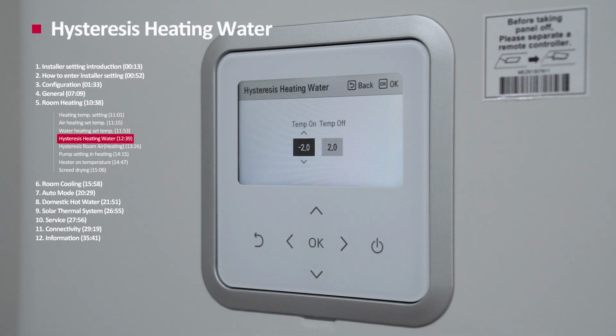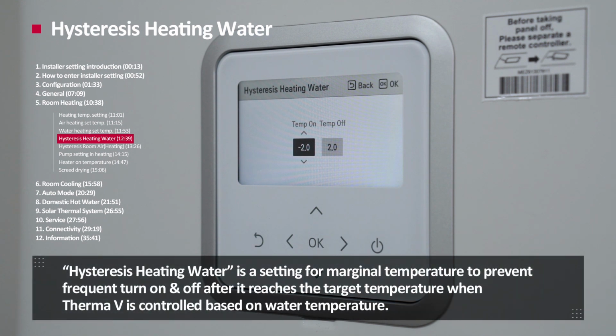Hysteresis heating water. Hysteresis heating water is a setting for marginal temperature to prevent frequent turn on and off after it reaches the target temperature, when Therma V is controlled based on the water temperature.